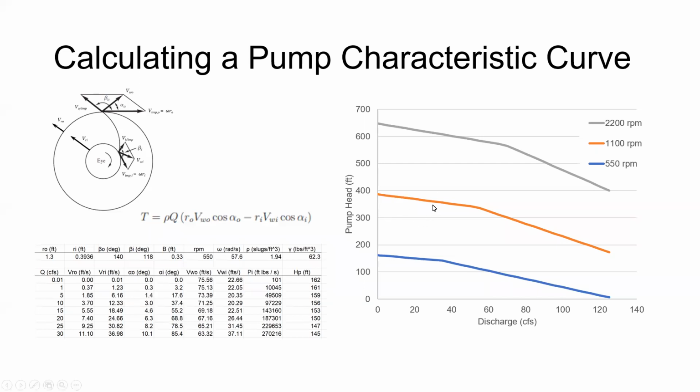That results in basically a family of pump curves for one pump device. And the family just represents different RPMs. So I've done this calculation. This is basically the torque and the speed to get for different flow rates. So the flow rate is going to influence these two velocity terms. And then this is what generates this kind of theoretical pump curve.